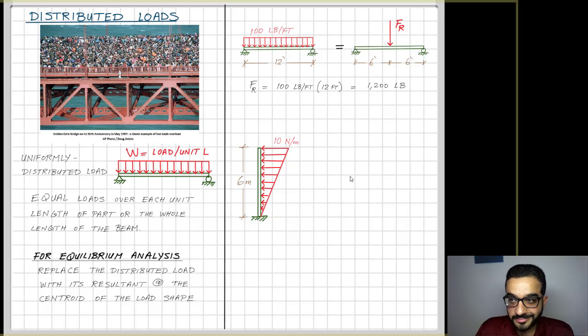You can do non-linear analysis, but we like linear stuff, right? It simplifies our lives. So now I have a triangular shape. So the question is, what's the resultant of this triangular distributed load, and where does it apply? We know from the information about regular shapes, the triangle, the location of the centroid, to where I can apply this resultant FR, is at a distance of 2/3 of the base from the head of the triangle. So 2/3 of 6 is 4 meters from the head of the triangle, which is the bottom point here.